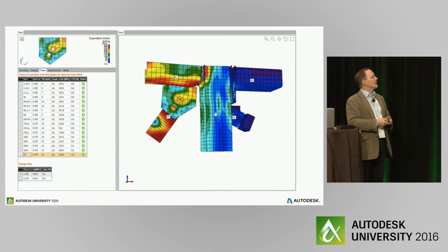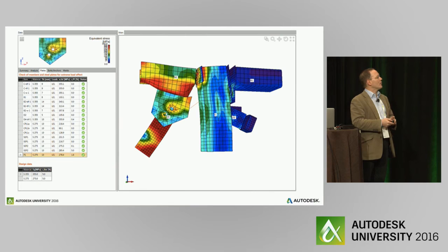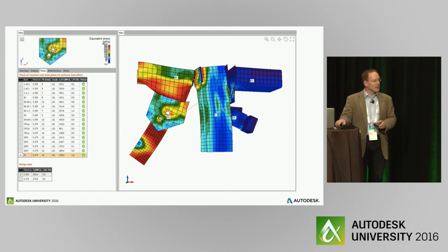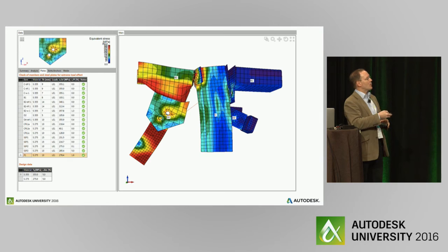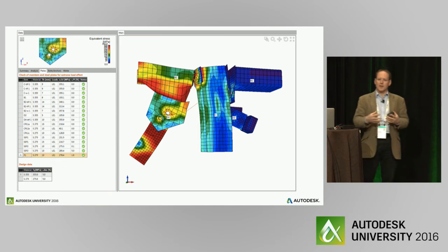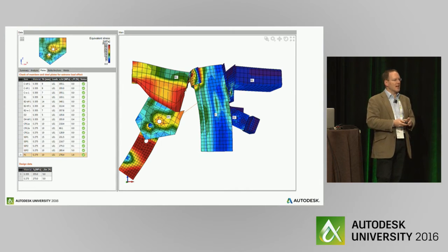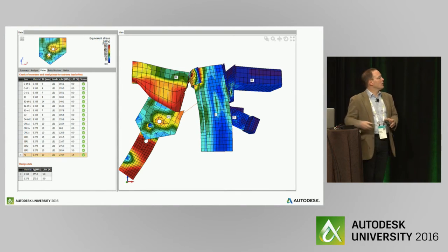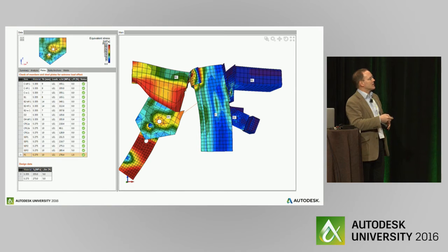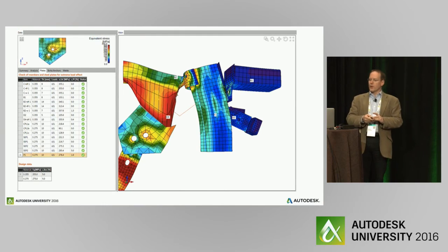The problem came when you look at the deflected output from this connection. So if you remember, there was a tension force in this top cord, which was having to be resisted by the brace. So all the plates were being pulled apart, and it wasn't a very stiff connection. And you can see that by the way that the connection was opening up. And you can see particularly top right, there is an end plate on this connection here, which is a tube, and that end plate was bolted below. Also, this was a PFC, a channel section, with the bottom web part being pulled down by the gusset attached to the brace. More obvious as you toggle through it.